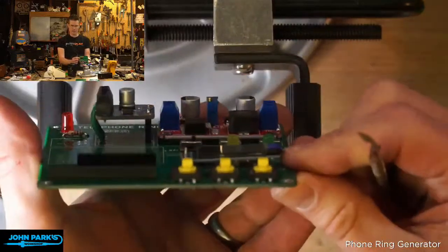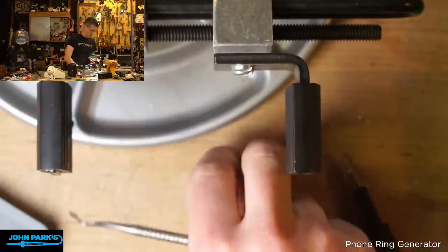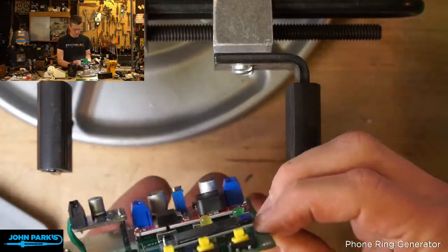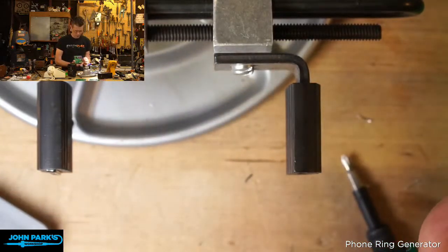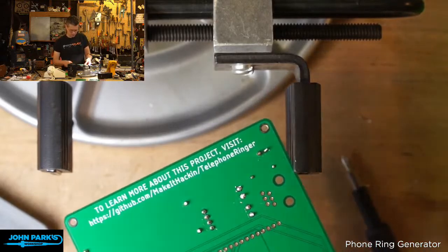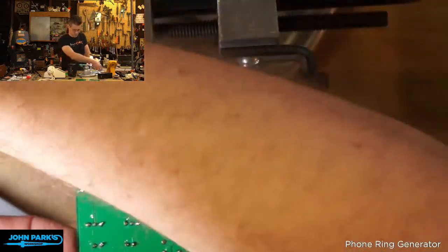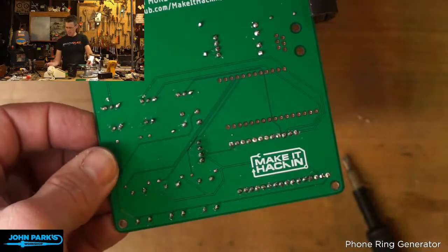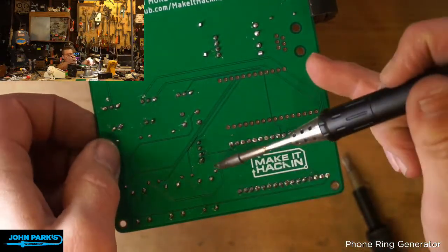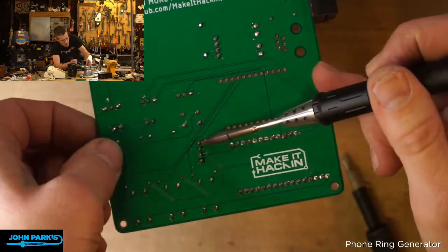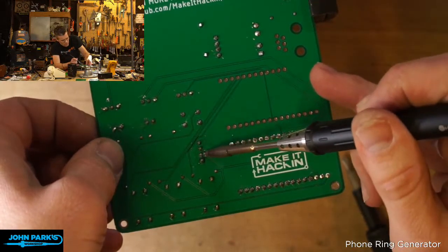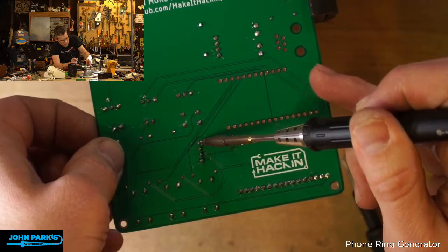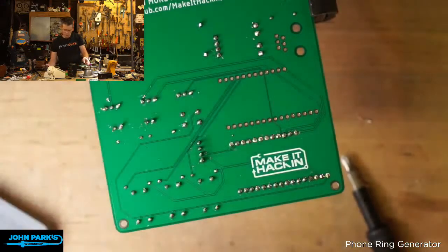Okay, so same thing. I have introduced an angle here that I'm unhappy with. That was all folly. So I'm going to go ahead and hold down on the PCB again and heat that. Try this time to avoid bridging things, and just try to be a little more careful. So let's go right here. I'm actually going to try to view it from below a little bit, if I can. Okay, I think I felt that move a little, so take a look.